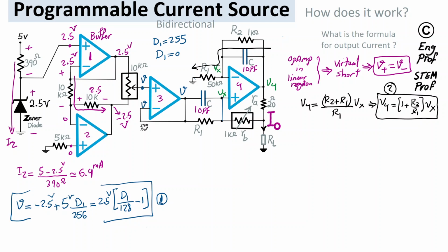Okay, so let's also consider defining V4 via this route. So what I can say, I observe that there is the output current I out, and also there is another current in, let's say, blue, like this, that is coming from V. So I can find V4 given these currents and the amount of voltage drop they cause. I can write effectively a KVL, or Kirchhoff voltage law, which is the sum of voltage drops basically. So I can say, using KVL